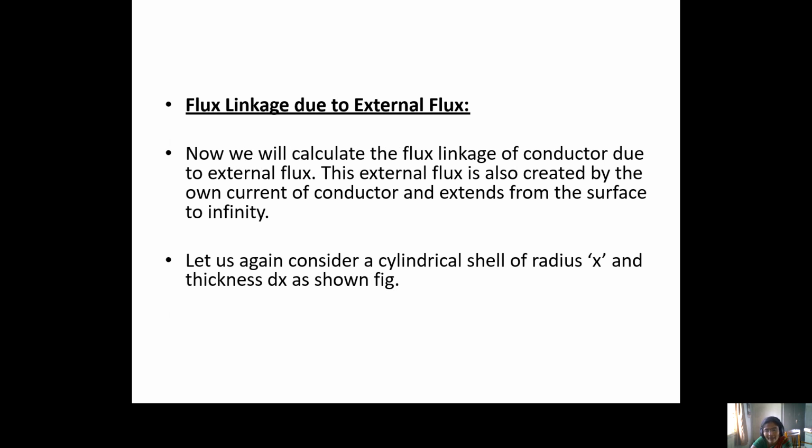Now you have to find out the external flux, the flux linkages due to the external flux. Now you will calculate the flux linkages of the conductor due to external flux. The external flux is also created by the own current of the conductor and extends from the surface to infinity. Internal flux means only inside the conductor, but the external flux is also created by the own current of the conductor and extends from the surface of the conductor to infinity.